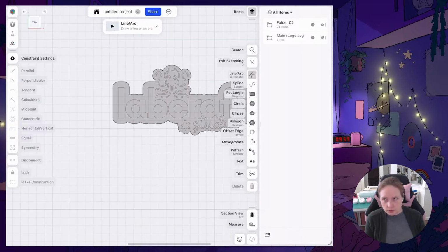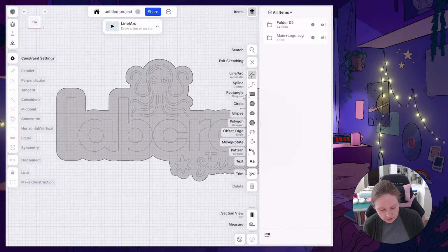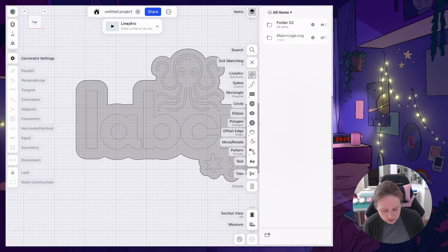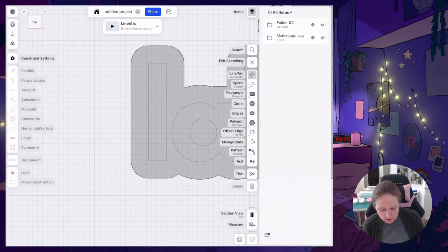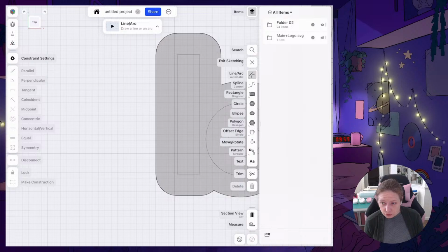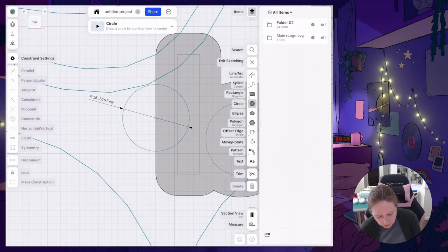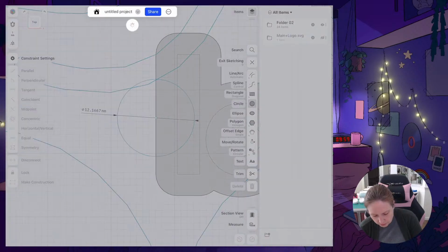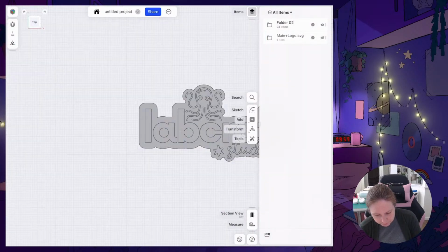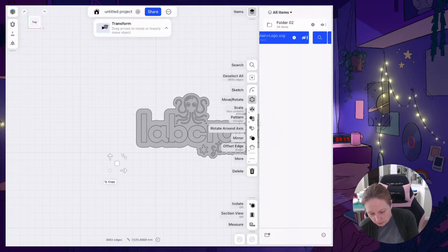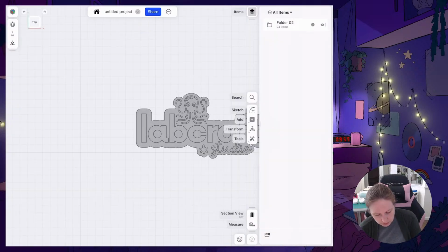So for instance, I'm going to add a sketch. So I've got this open and you can see it. And this looks like it might be an area where I need to add a bigger sketch, like add an additional area to the keychain and then use that to make a hole. So for instance, I've got this here. So I'm just gonna do a simple circle, and I'm going to pull out from here. Oh, I've got extra here. Before I do that, I'm gonna go ahead and just delete that sketch that I already had. I don't need it anymore. It's just gonna get in my way.